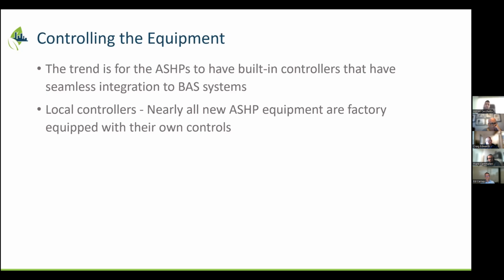The hard part these days is using the various forms of documentation that the manufacturers provide to really understand what the heat pump does, how it does it, what logic it takes on its own. Because at the end of the day, it's not really our job specifically to control the inner workings of the piece of equipment. We're really setting the stage for the equipment to operate at its optimal point. And I think that's a really important thing to remember. And like I said, Craig touched on that a few different times, where if you don't have all the support systems and all the parameters of everything else that's going into this working properly, you're really not going to get the gains, and you're really not going to get the efficiency. And you might have some equipment longevity problems later on due to short cycling and things like that. So I think that's a very important key piece to remember when you're thinking about these things.